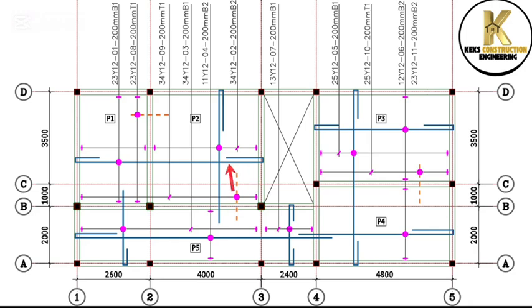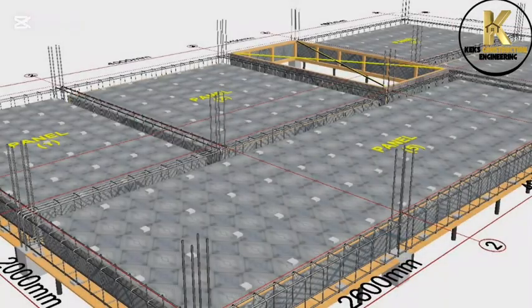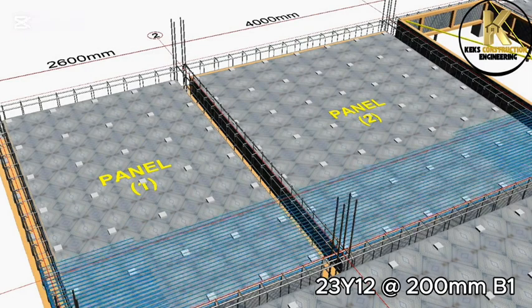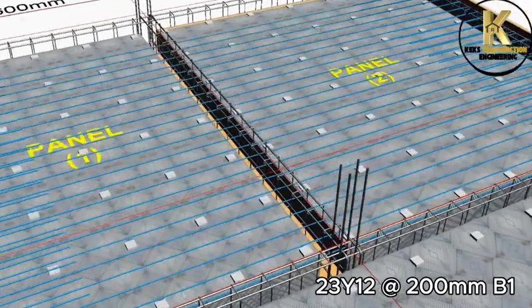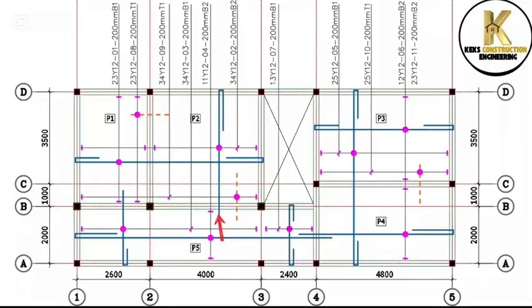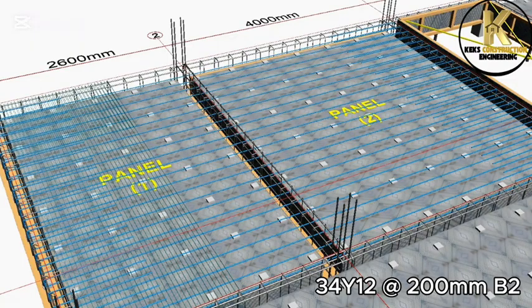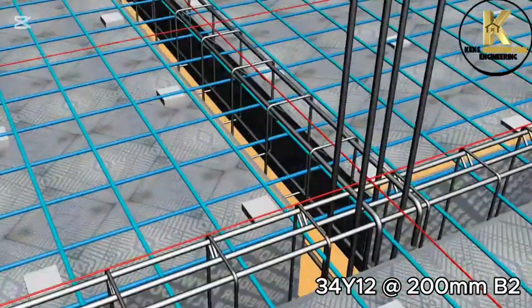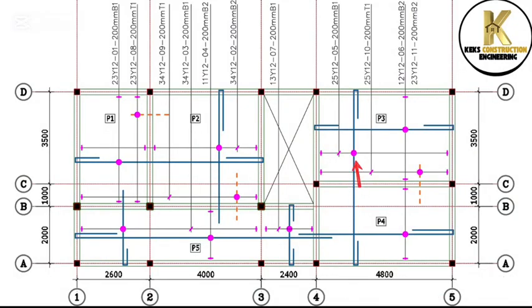Now, let's practically execute this first bottom bar on site in panel 1 and 2. 23 Y12 at 200 mm center-to-center spacing, B1. 30 Y12 at 200 mm center-to-center spacing, B2. 25 Y12 at 200 mm center-to-center spacing, B1.